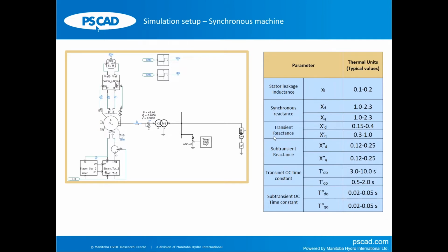One thing that is good practice to remember is that you will have to enter the machine electrical data, XDs and XQs. Be mindful of your data entry. These XDs, XQs, and TDO double primes, for practical designs, fall within a typical range, right? Sometimes your data sheets may have errors or mistakes.